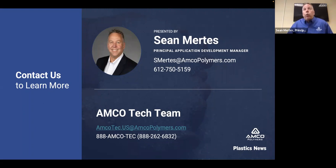Recovery is a large portion of it. And that's the big question: can I get back fast enough? If you do thin wall molding, and I'm working with a lot of customers that do, back in the day, like I said, I've been doing this for 30 some years. I would say back in the day, 80 thou wall, 80 to 100, was kind of standard nominal wall. Now when I talk about standard nominal wall, I'm at 60 and maybe even 40 thou. So things are getting bigger, better, faster, stronger, thinner, and things are changing.